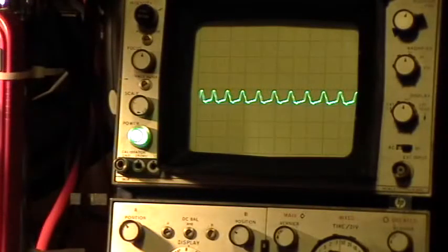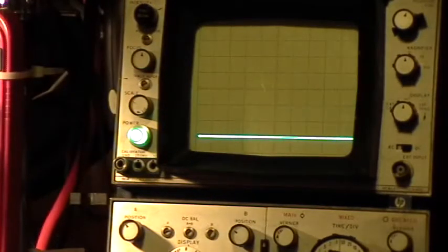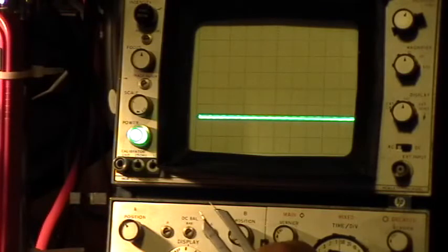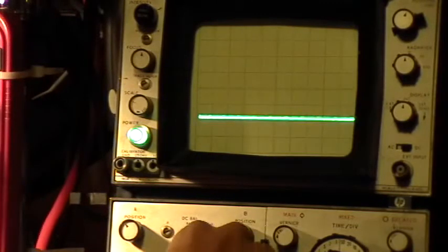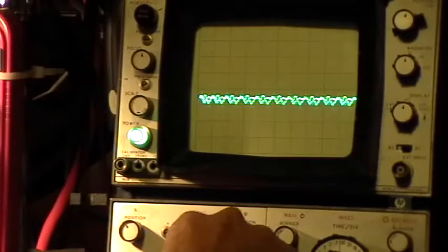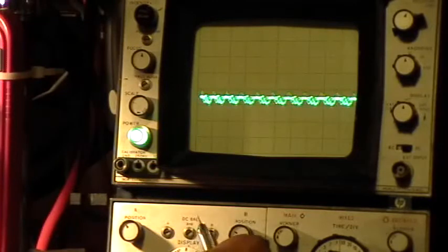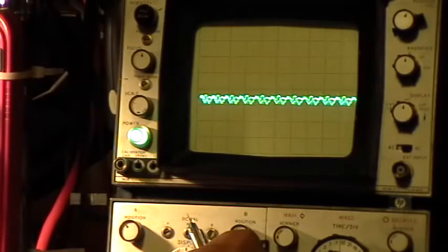Now we'll go down one more to the positive pole of the least positive battery in the stack, the negative battery. You can see the voltage there, but the oscillations are not big enough for me to get a trigger, so I'm going to change the amplification to 5 volts per division instead of 10. Let's see if we get a good trigger there.